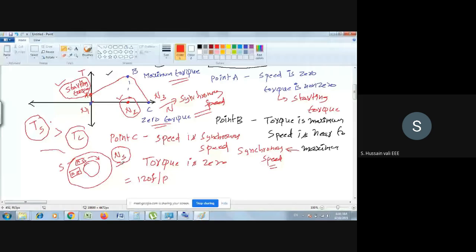So the magnetic field in the air gap is rotating with synchronous speed. Now, for example, the rotor here is rotating with some speed other than synchronous speed. Say synchronous speed is 1200 RPM, whereas the speed of the rotor is 1000 RPM. I told you already that the rotor also has a magnetic field, so it also has some magnets. One magnet is rotating with 1200 RPM, the other with 1000 RPM. When both magnets are running with different speeds, there is a relative speed. What is the relative speed in this case?